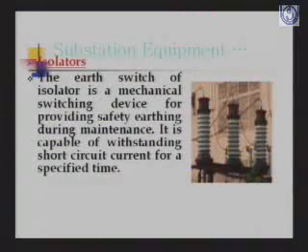The isolators also have an earth switch, and the earth switch of the isolator is a mechanical switching device for providing safety earthing during maintenance. It is capable of withstanding short circuit current for a specified time.